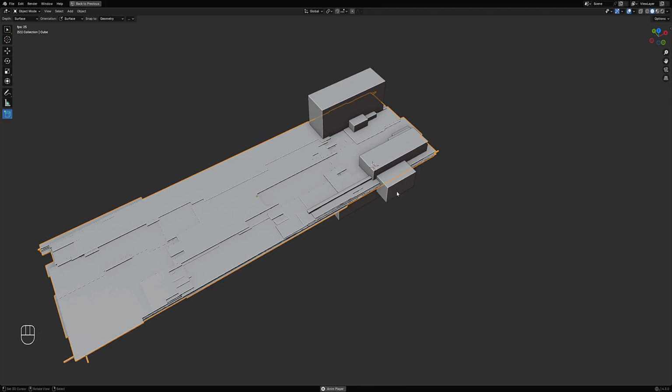So what you do is select the objects you want to copy it to. So for example, like that, and the last object or the active object should be the one that has the geonode settings that you want to copy, and then you just use the copy command.